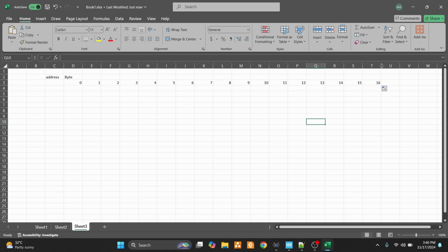We'll take 16 only. Here we'll put the address 0x000000, 24 bits of address, so 3 bytes of address. If you go on writing data from this to 000010, 000020.